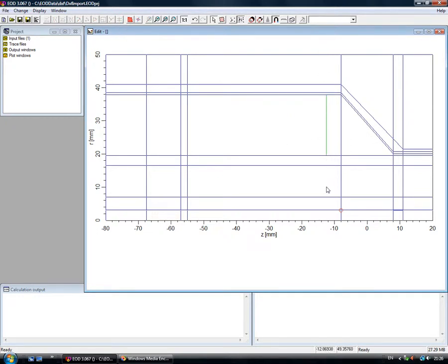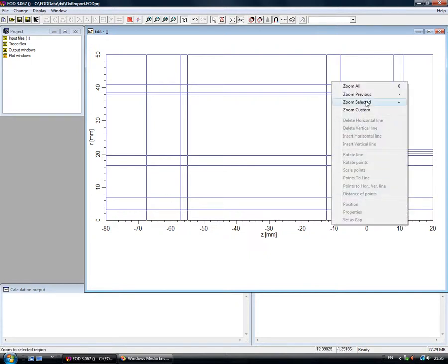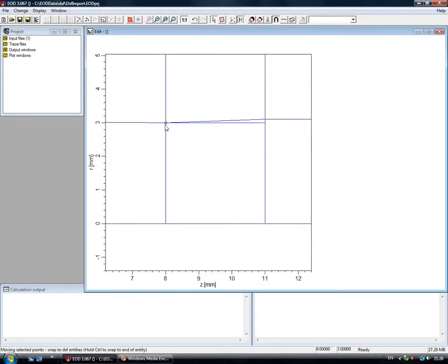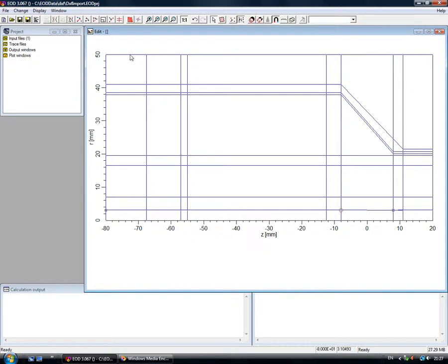Okay, now I need this vertical mesh line to have coarse mesh to define the core. Okay, we have coarse meshes and can fill materials into the mesh. Now when we look here, this coarse mesh line is not correctly set in this position, so I will move it a little bit down using the snap function and put the whole line to the correct position. Now it is okay. We can save the design because we have done a lot of work.